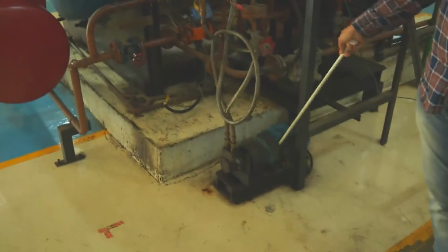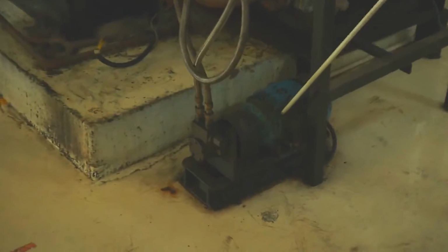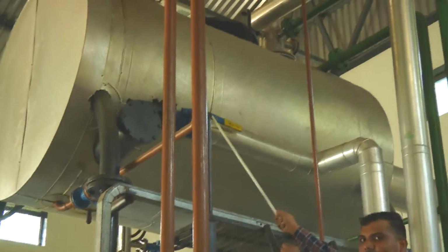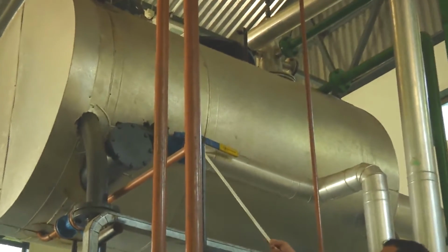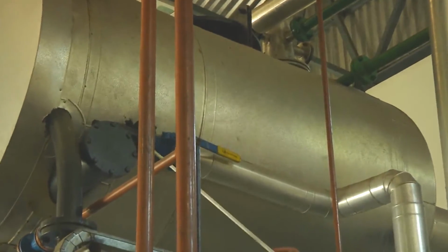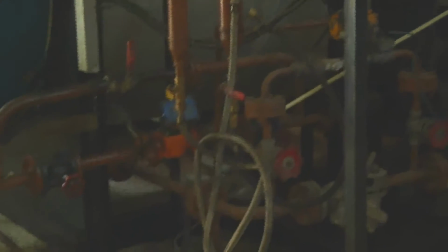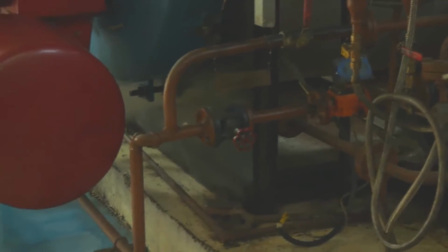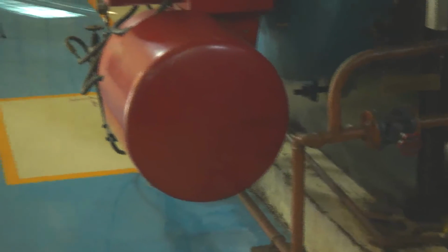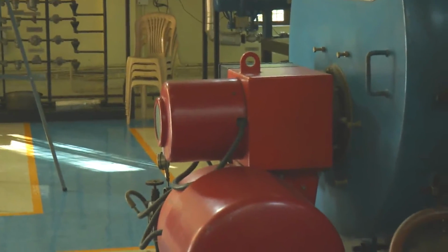This is our fuel pump. With the help of this fuel pump, we can top up the fuel on the overhead tank. This is our top up line. The next part is our fuel line for the setup. Fuel comes from this line to the setup. It comes to the filter, then it goes to the fuel meter. This is our fuel meter, and it goes to the burner. This is our fuel circuit.